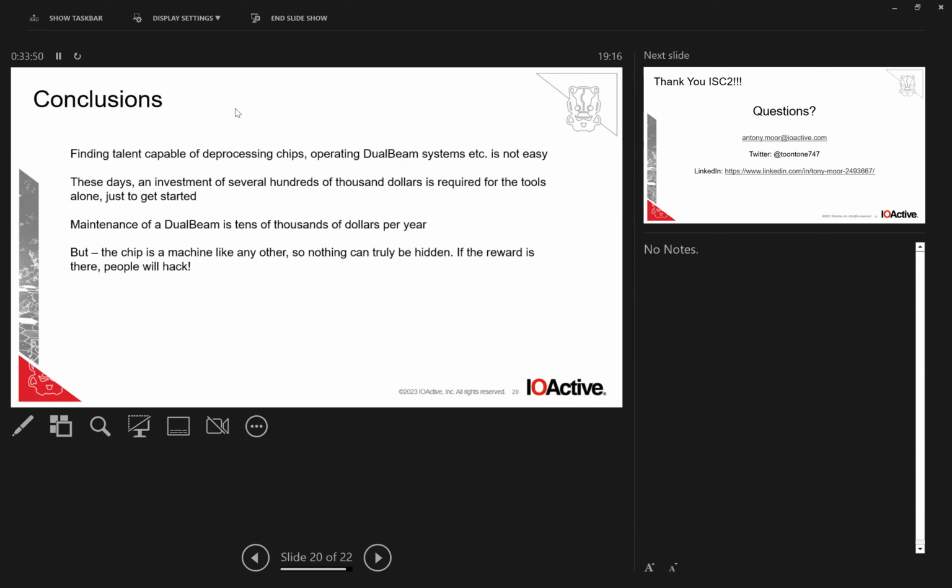These days, devices have the circuitry made out of copper. Many, many more layers and much smaller, of course. That makes things very difficult because the tracks are copper, interconnects are copper, and it goes copper all the way down. So you can't use wet chemicals because the chemical will just eat all the way through layer by layer and you can't control it anymore. So you have to rely less on chemicals these days to deprocess, more on things like ion beams. Plasma etchers are still used quite a bit, and basic mechanical polishing, but with more advanced systems.